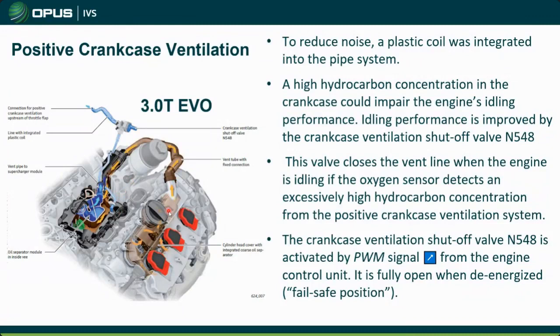And so one of the reasons why they put this whole system down in the V here is to keep it warm. One of the reasons they don't mind the coolant flowing through here is because it keeps it warm. Right, heat is going to be your friend when you're trying to separate oil from air, and prevent that freeze up from occurring.